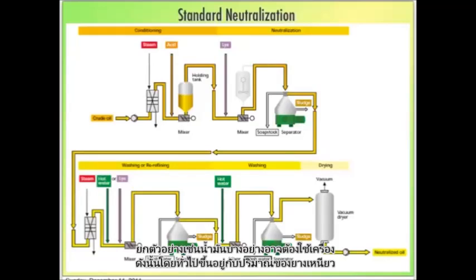For example, some oil may require some conditioning. So basically, depending on the amount of the gums and free fatty acid, it may require some pre-degumming step.